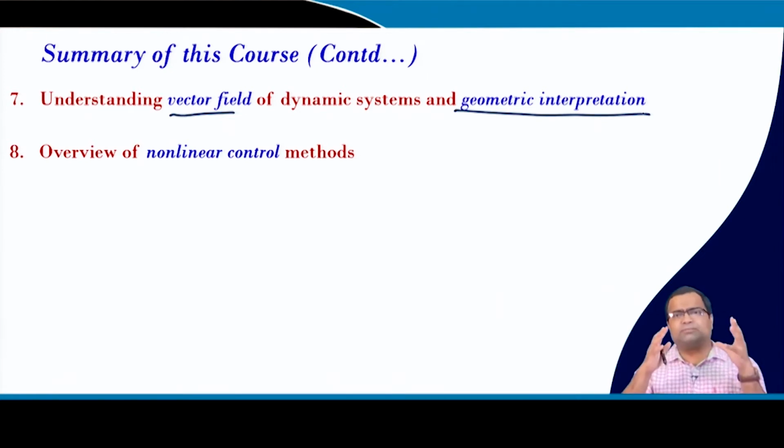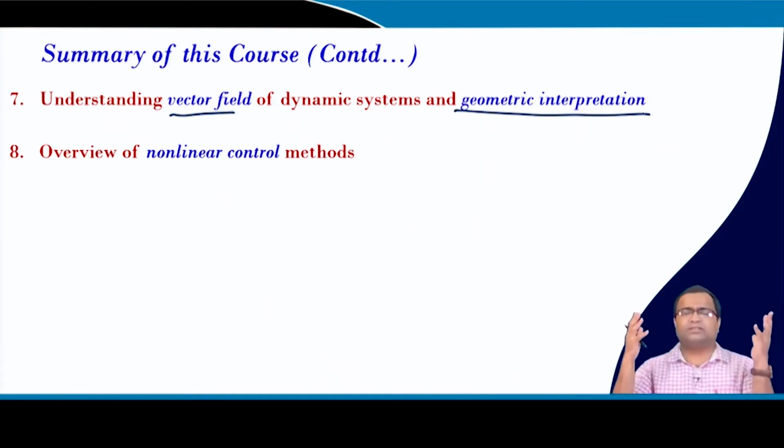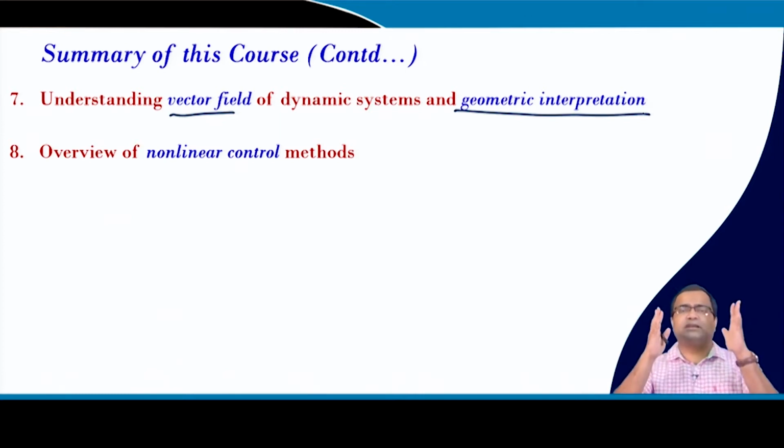Then we also discussed the switching model, because even the average model actually ignores the switching ripple information, so we cannot further improve the performance. Then we discussed that if we incorporate the switching model, we can go to the fastest response and achieve time optimal recovery, which actually gives us the slew rate limit of the converter. So, we can reach up to the slew rate limit.